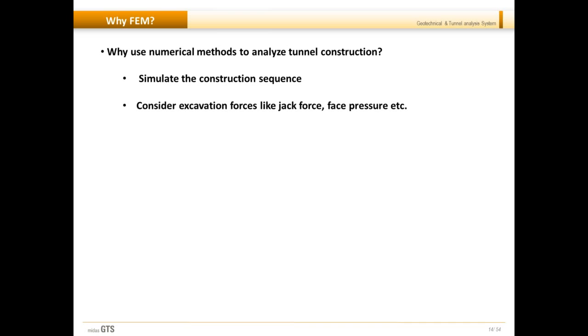So first, to simulate the construction sequence, and this is all we will be talking about today, how to simulate the construction sequence. To consider excavation forces like jack forces and face pressure that are occurring, and you will see how two same scenarios could differ if the construction staging is not considered in between.